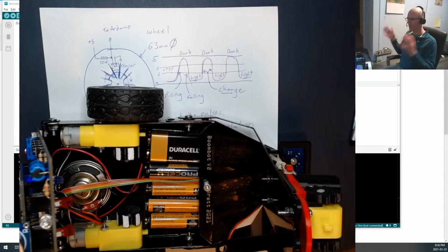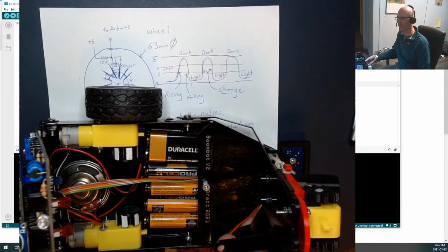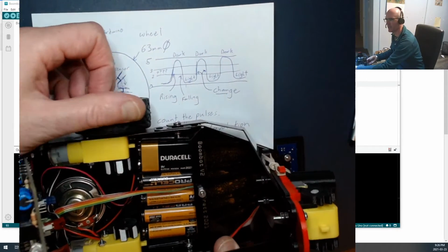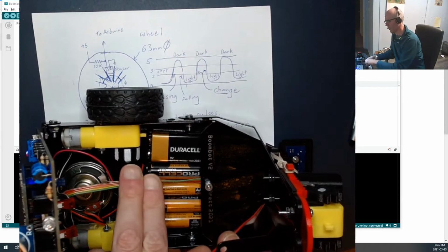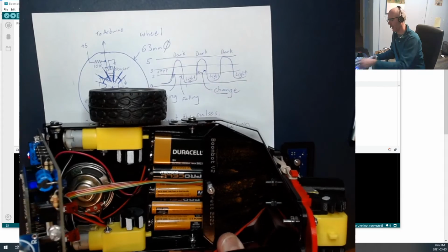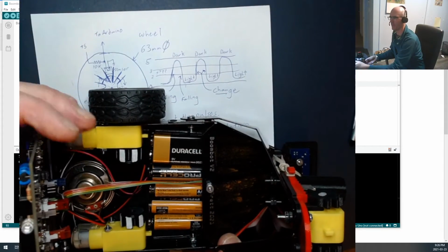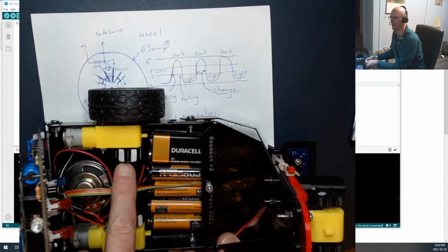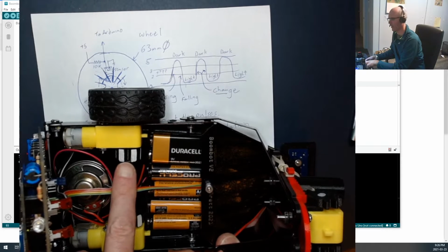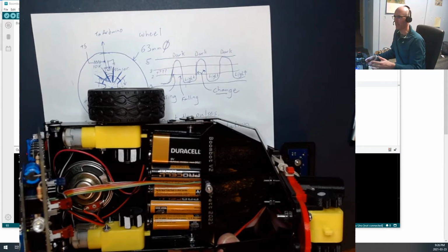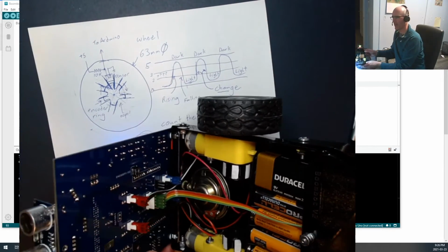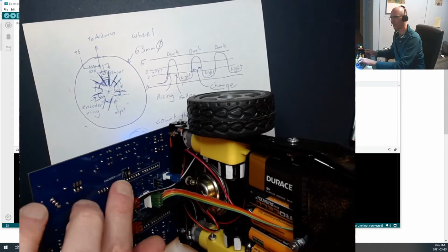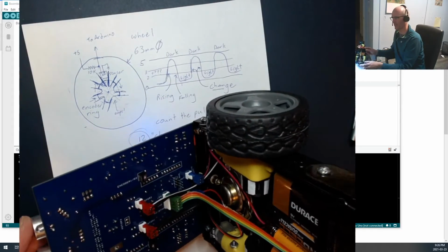Interrupts is what we want to talk about today. I brought the robot up here onto the desk, and you'll remember when you were putting this together, you were installing these little things inside called encoder rings. The instructions said it was really important that you made the outside of them white and not the valleys down here. We wanted those to be nice and dark black. After doing the edge detection and line following lesson, you probably realized that's because we have a QRD1114 sensor right down here.